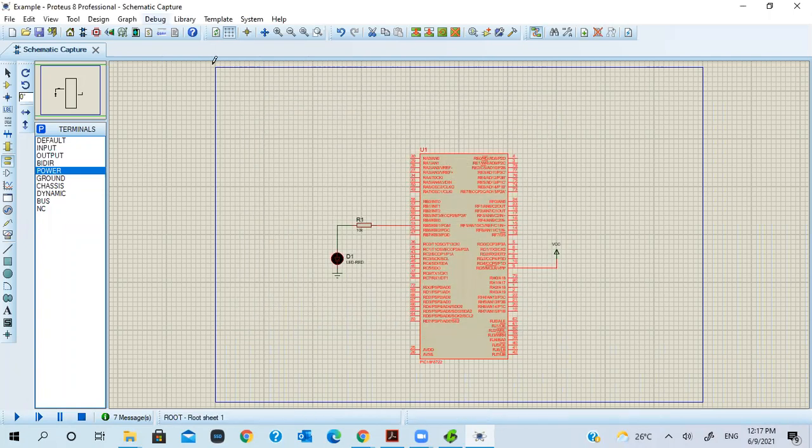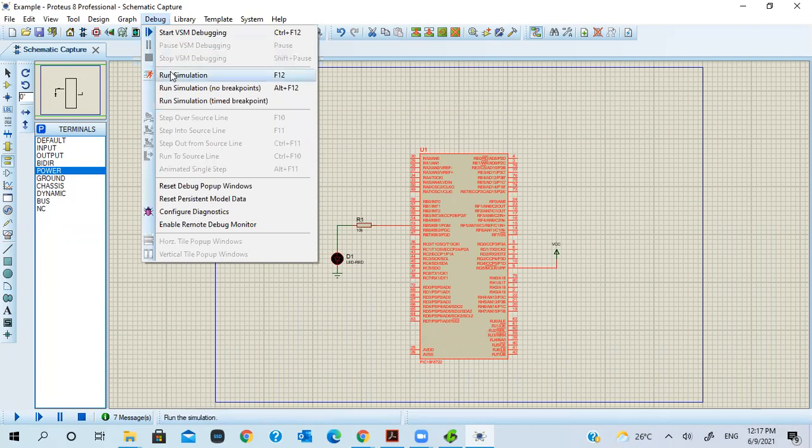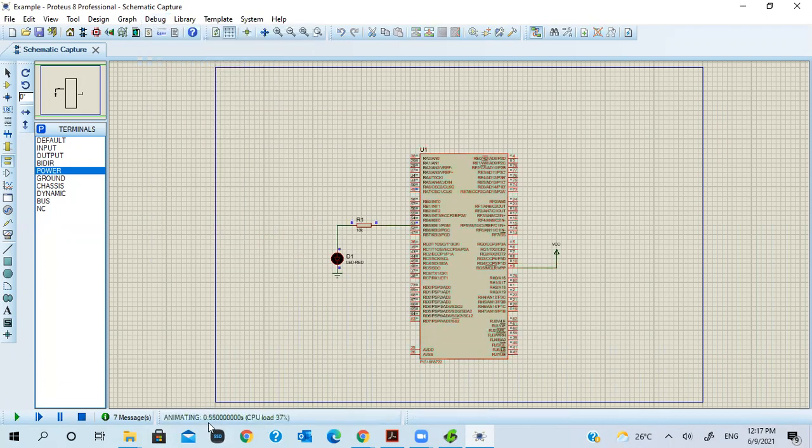Again, you can see now I've set it to 20 megahertz. I haven't changed the code. I've just changed the processor frequency. Now remember, my code has a 20 megahertz clock, while the machine is now set at 20 megahertz, and we need to generate a 1 second delay. Let's see, are we getting a 1 second delay? At 1 second, it will turn on. At 2 seconds, it will turn off. At 3, on, off. So you can see that now we are getting a 1 second delay.